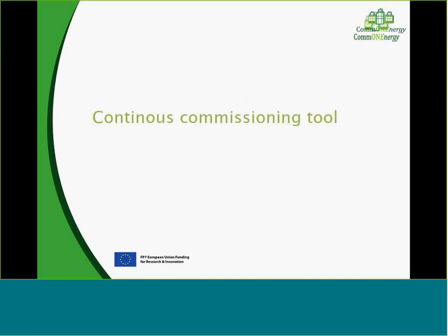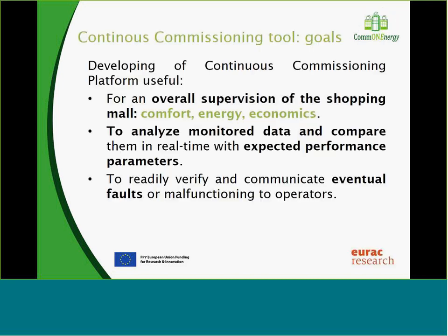Now I want to move on to the continuous commissioning tool. The continuous commissioning tool has several goals. First of all, it's used for an overall supervision of the shopping mall, from a comfort, energy, and economic point of view. This tool is made to analyze monitored data coming from the building monitoring system and compare it with the expected performance of the building.